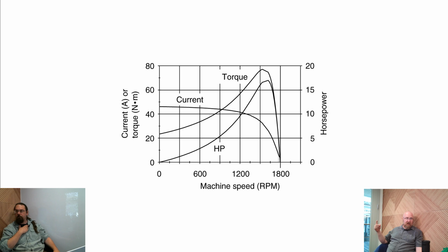It's not going anywhere near its full speed, even though the moment you energize that magnetic field, the magnetic field is going at that speed. Yes, there's a lag between the rotor and the field. The rotor has to pick up the momentum to follow it physically. And what's happening is it's slipping a lot at the beginning, and then it eventually catches up. As it's slipping less and less, we get higher torque.